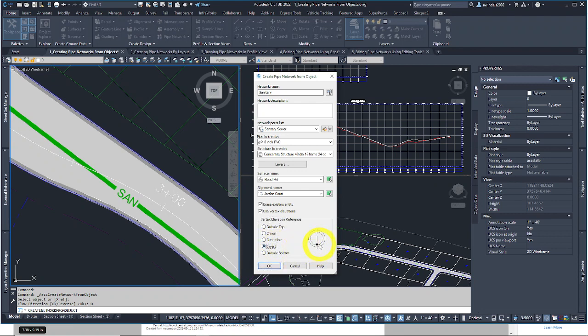This is where the water is going to be sitting, basically, on the bottom inside of the pipe. This is a very critical elevation to know, called an invert elevation, especially with gravity. That is a very critical elevation to hold, maintain, and base off of, if the gravity is to be going the way you want. And lastly, outside bottom of a pipe. We'll just keep this on center line, turn this off, hit OK.